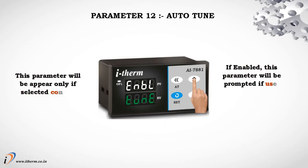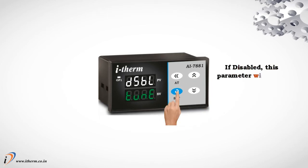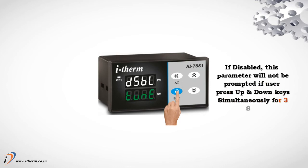Parameter 12, Auto tune. This parameter will appear only if the selected control action is PID. If enabled, this parameter will be prompted if the user presses the Up and Down keys simultaneously for 3 seconds. If disabled, this parameter will not be prompted when the user presses the Up and Down keys simultaneously for 3 seconds.